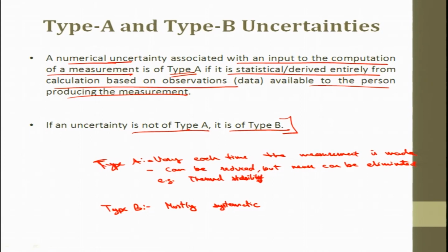If I pick a specific case, there are many systems, both mechanical and electrical, that can be sensitive to temperature. For instance, if I pick a strain gauge that depends upon the resistance of the metal foil that makes the gauge, the wire resistance depends upon the temperature. And if a gauge is used in a changing temperature environment, the output caused by the temperature change can wrongly be attributed to changing strain.